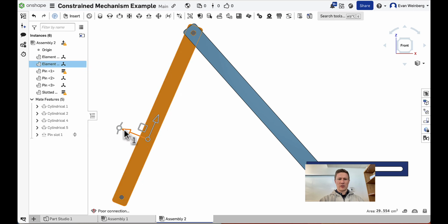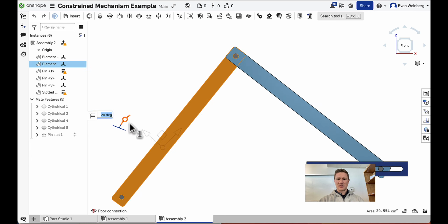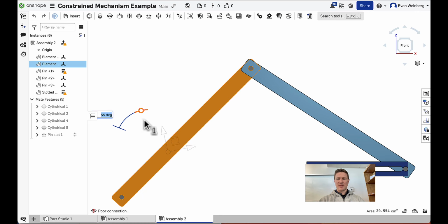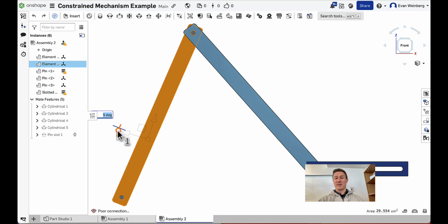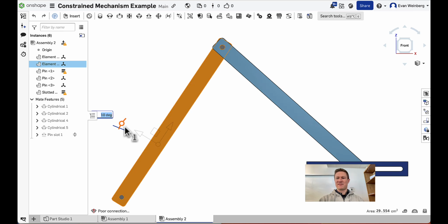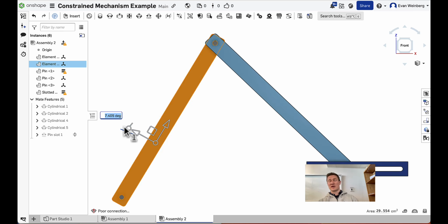So now you'll notice as I move this around, when it gets to the maximum distance of 9, maybe it's only 8, it doesn't move any further, and when I try to move it further past that left end of the mate, it gets stuck. So we've now constructed a mechanism with a couple different parts and a specific mate that makes it so that we're now simulating a series of parts that we could actually build here in the Maker Lab at school.